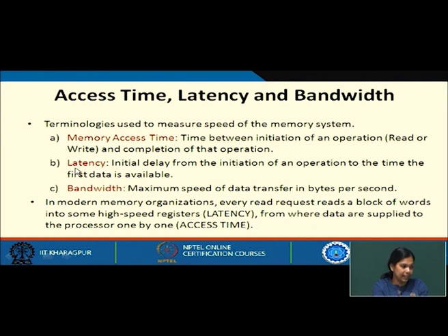Next is latency. Latency is the initial delay from the initiation of an operation to the time the first data is available. Let me tell one thing at this point of time: when we access a particular location in the memory, we do not just retrieve that particular data, we always transfer a block of data.